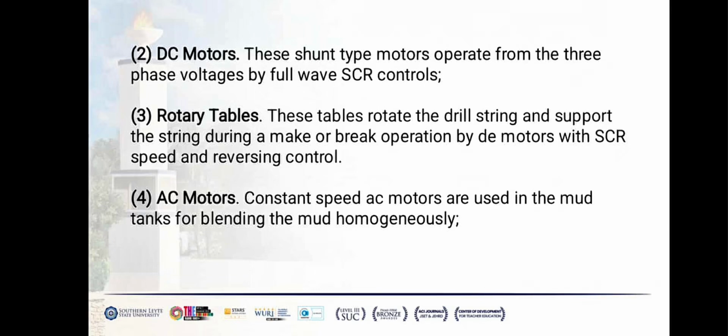2. DC motors. These shunt-type motors operate from the 3-phase voltages by full-wave SCR controls. 3. Rotary tables. These tables rotate the drill string and support the string during make or break operation by the motors with SCR speed and reversing control.